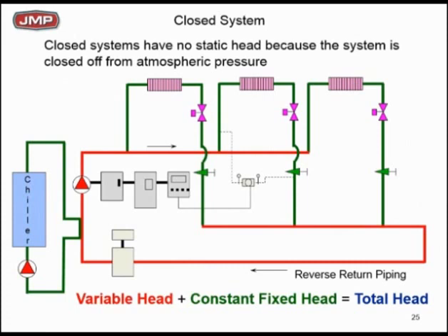If I cut my flow in half, the friction becomes 25%. It's back to that square thing we talked about. So that's the only thing really changing the pump speed in the overall pump head loss calculation: the piece of the pump head that's variable, that's changeable with flow.